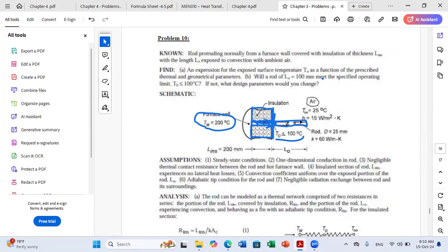So you have two opposing effects for the conductivity. It's not a normal fin here. That's why we need to consider a certain design to optimize the value of conductivity of the fin. And also we can optimize the length L0.